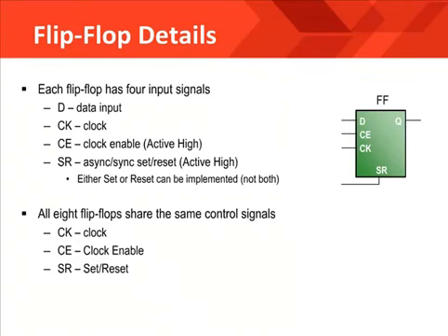This is important because your synthesis tool should be able to map the set or reset to a LUT input if it is synchronous. This gives you more flexibility that is necessary for the tools to pack the most logic into the FPGA and get high speed, since all 8 flip-flops are required to share the same control signals. So our recommendations are to design for active high control signals and build with a synchronous set or reset.